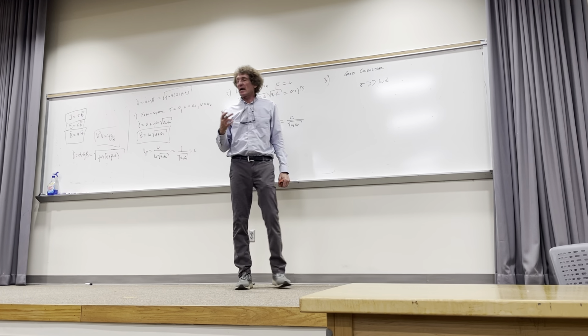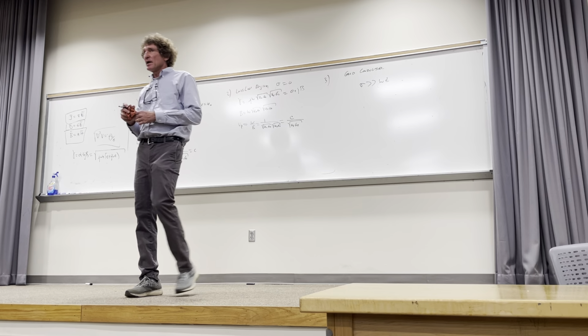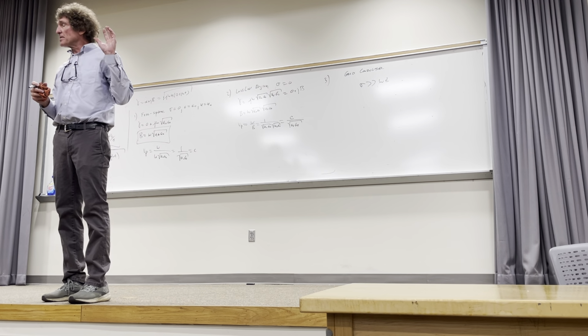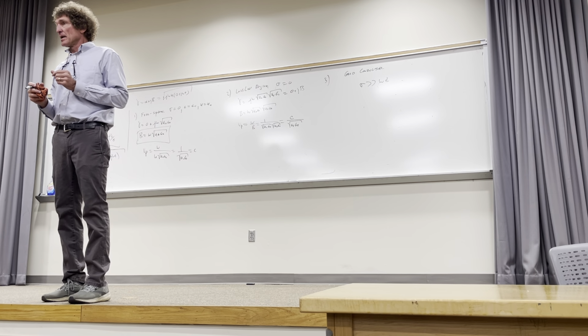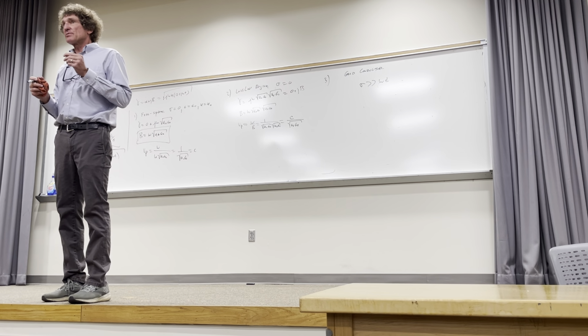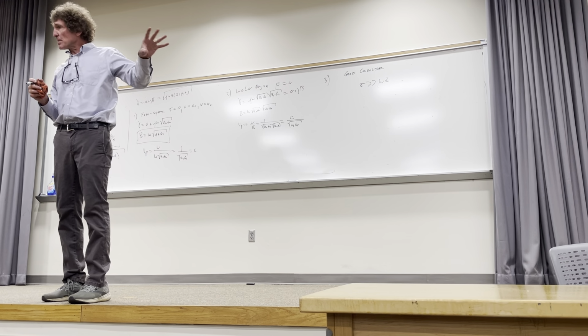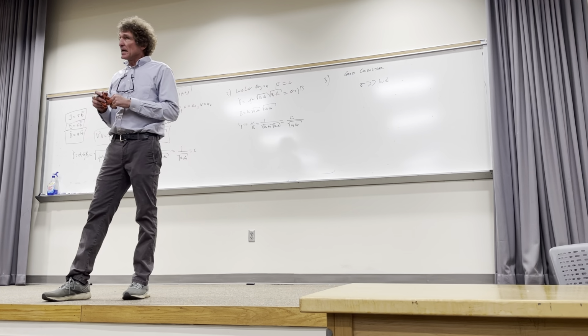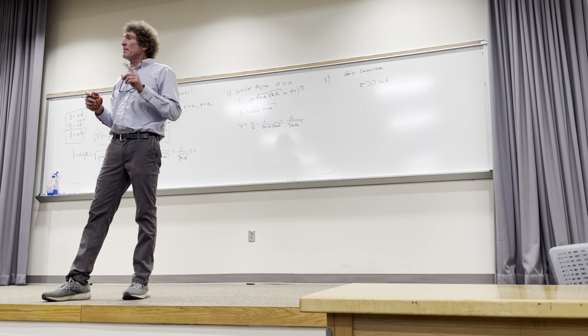Now remember, omega epsilon is a term that's weighting the E field, and it's related to the displacement current. Do you all remember that? We have the partial of D with respect to t, that's displacement current. Well, the partial with respect to t is j omega, and D is epsilon E. So j omega epsilon E is displacement current.